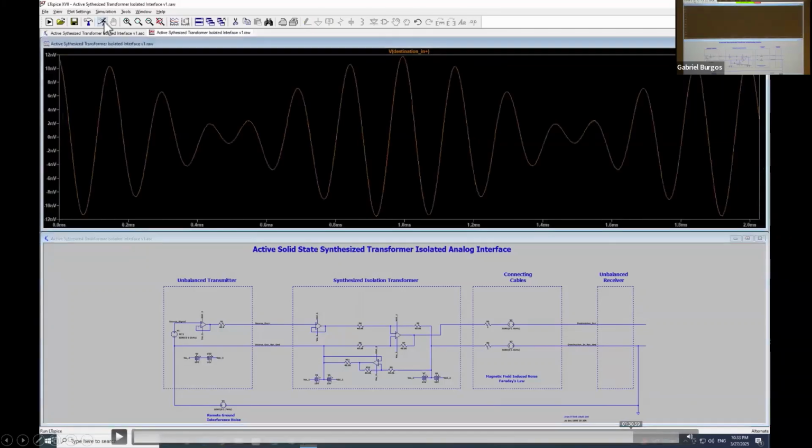It's all pre-recorded. But I put large noise signals into the loop here. We got one noise in the ground, talking about a ground noise. The ground at the source of the signal is often at a different potential than the ground at the destination, and so you get circulating, you get a voltage difference between the source and where you need the signal. Then you also get pickup in the wires. Wires are known to pick up magnetic fields. That's Faraday's law: a changing magnetic field will induce a voltage in a wire, and that can be picked up as noise in an audio system.